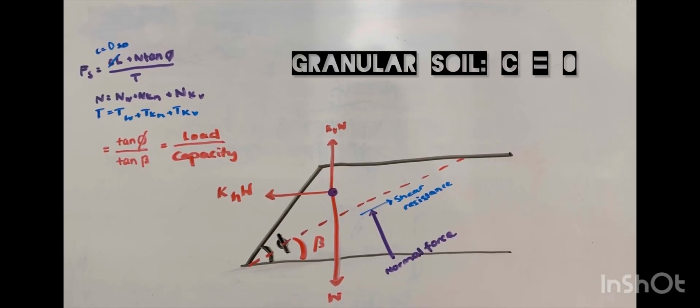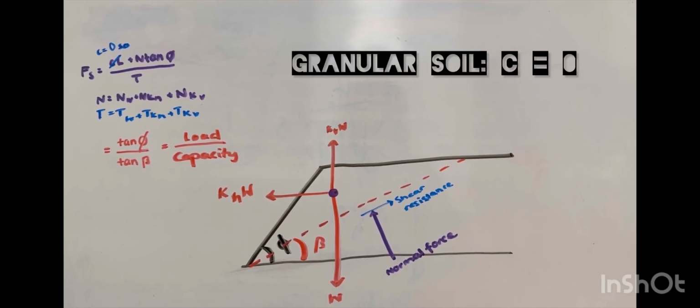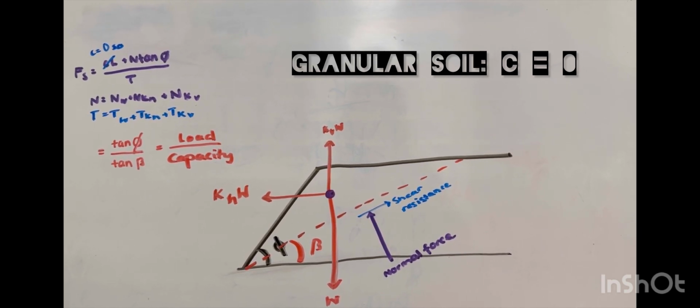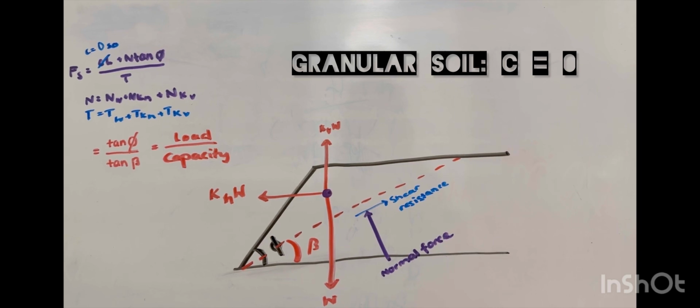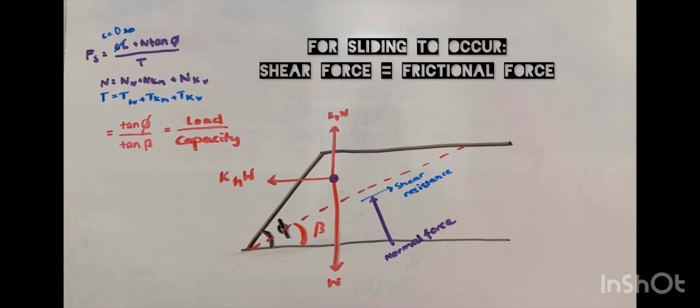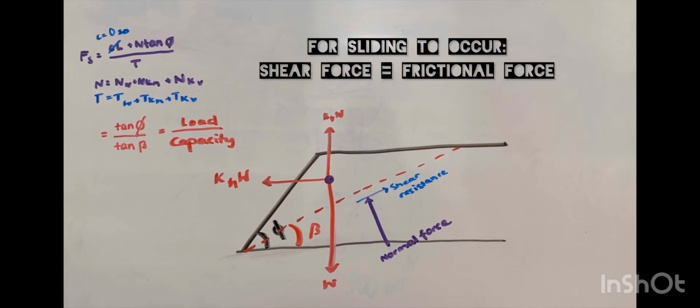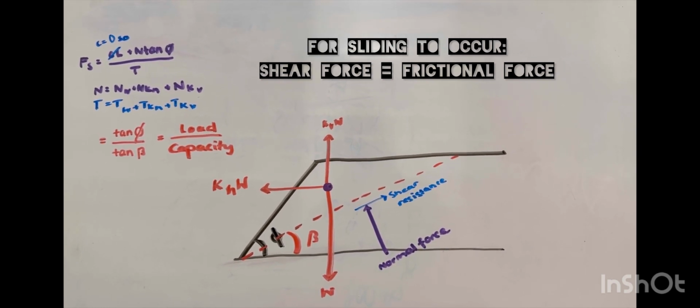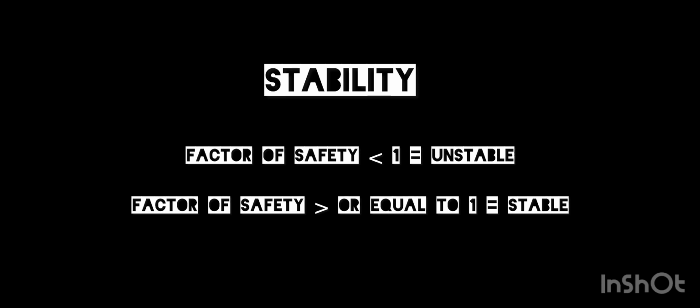In the top left equation, Fs denotes the factor of safety of a slope, which is dependent on the cohesion of the soil, the length, as well as the normal and shear forces on the slope. In the diagram, the earthquake is modelled as two static forces in the horizontal and the vertical components. This is called pseudostatic slope analysis. Using the variables in the diagram helps us figure out the factor of safety. The equations here show how that relates to the stability of the slope.